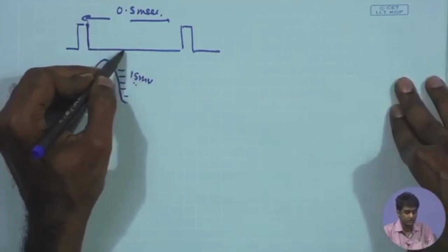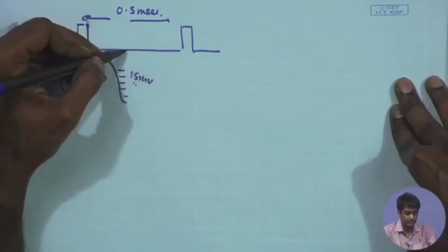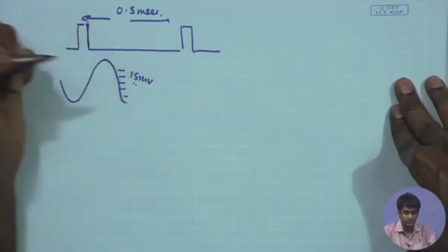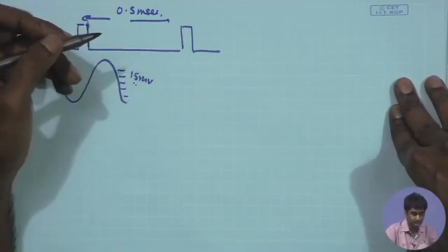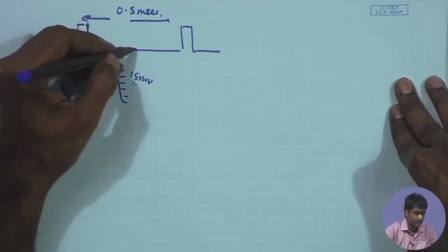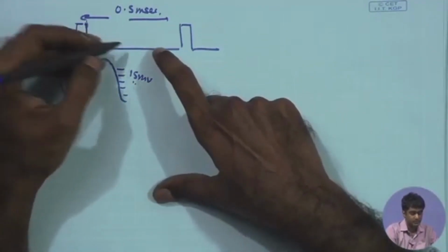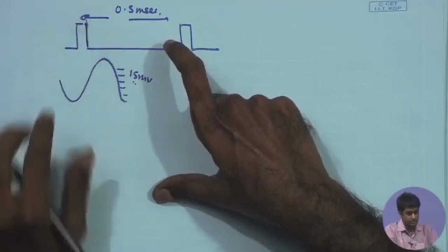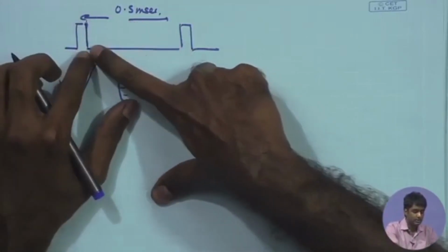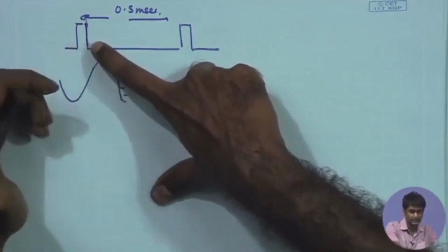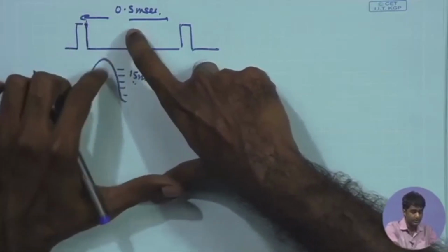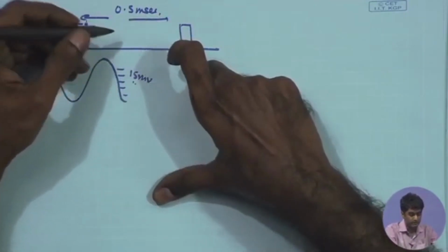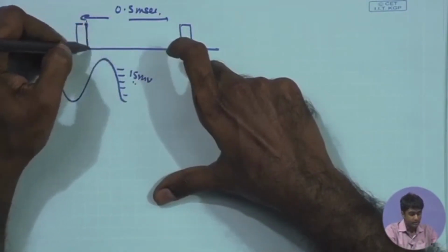If the Vref reaches the input signal quicker, that of course means the input signal is smaller, and vice versa. That also implies that a smaller input signal means the reference signal reaches the input quicker, and the comparator output goes down faster or earlier.